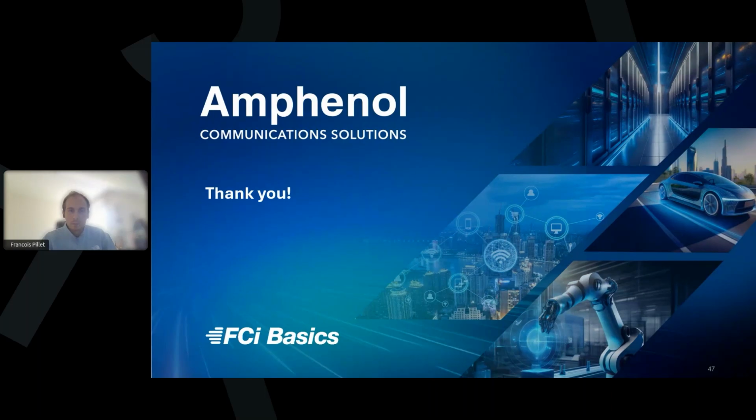Question number 1. What are the main factors to consider when selecting a signal interconnect solution for PLC applications? To me, there would be 3 factors. First one is reliability over time. We know that PLCs need to operate in demanding environments with high stakes. So if there is any issue or drop in the production line, there are high consequences. That's why the connectors that end up on the bill of material need to be reliable and industry proven.